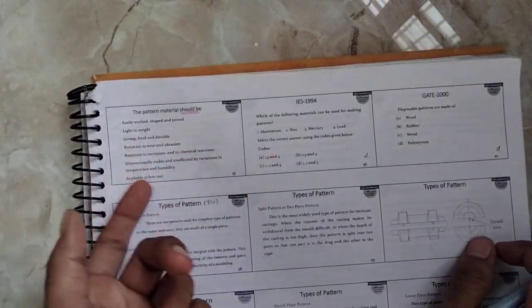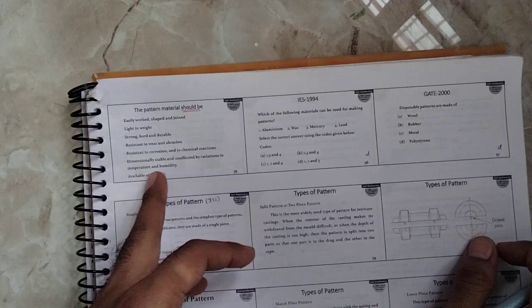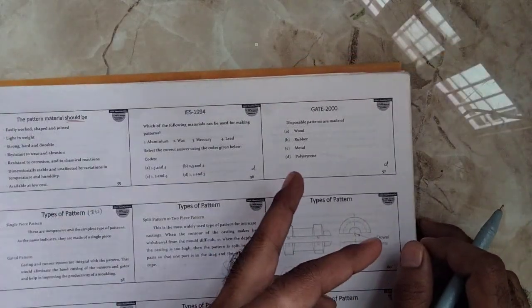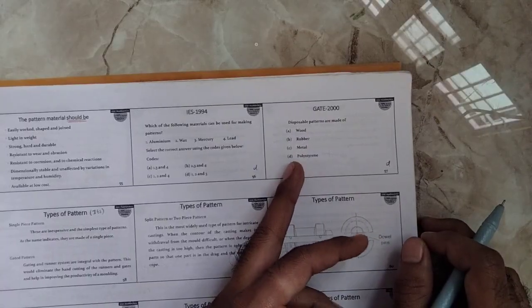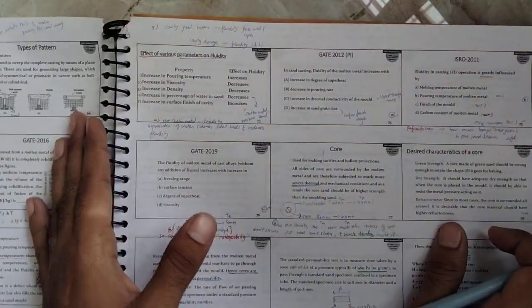Sometimes you can see plastic material also being used in full mold casting. Expanded polystyrene is used. Investment casting uses a wax pattern. Each and everything I just explained. So pattern is just a normal thing. It is resistant to corrosion and chemicals, and dimensionally stable. It is low cost, and easily obtained, light. This full pattern is generally made of polystyrene. This one pattern is a normal thing, not anything that much.